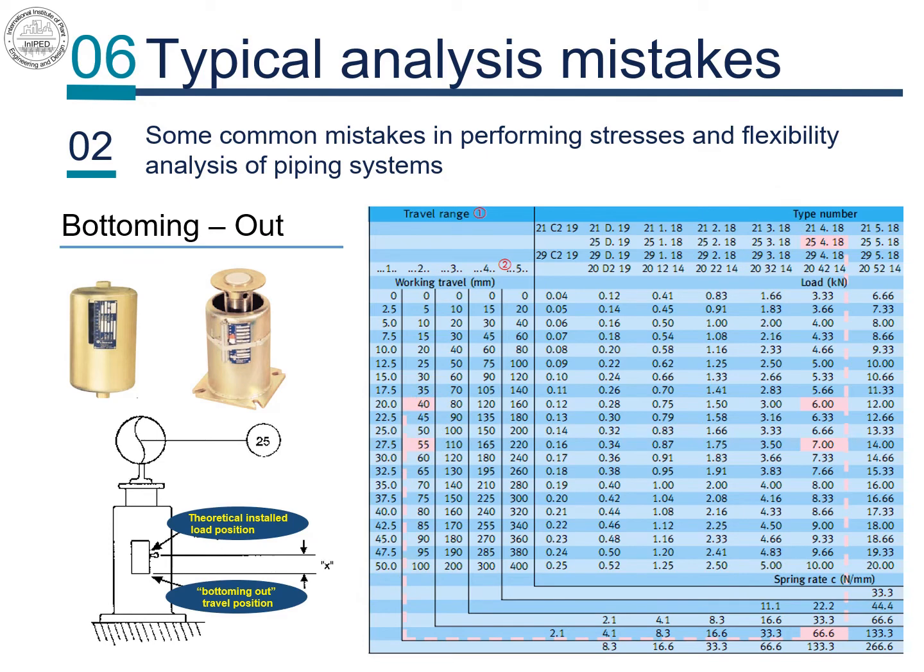The initial load, so-called cold or installation load, is set on the spring to be 6 kN. In other words, after removing spring locks, when the pipe is already sitting on the spring which has been factory pre-compressed, the spring will release a reaction force on the pipe of 6 kN. This load will, according to stress analysis, keep the forces on the piping system in equilibrium, and the spring will be in its theoretical installed position.